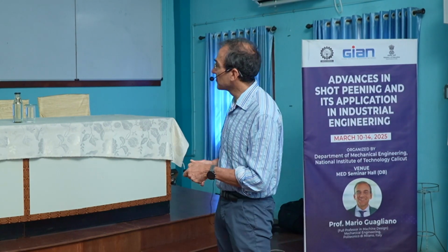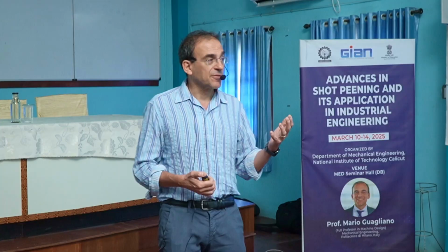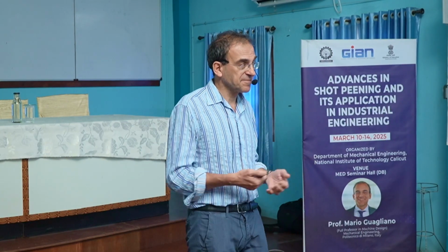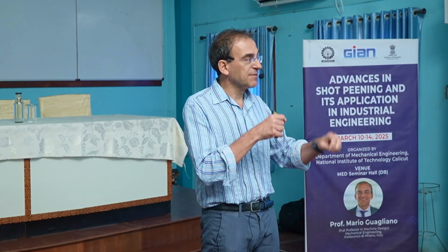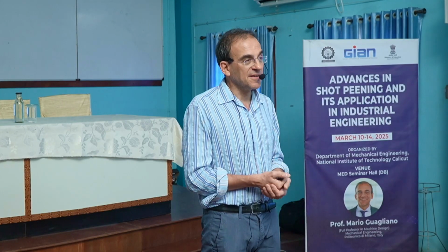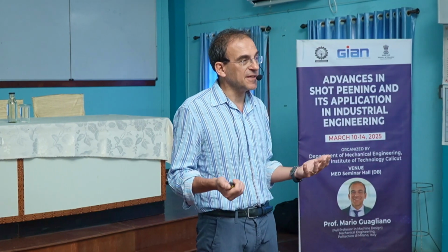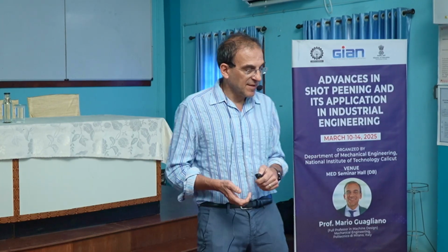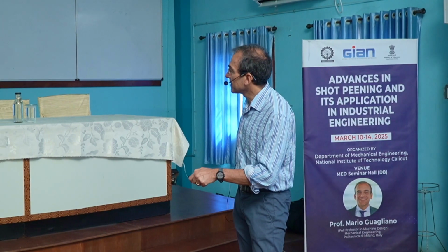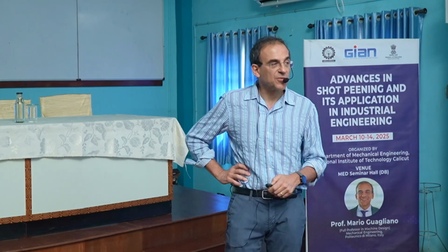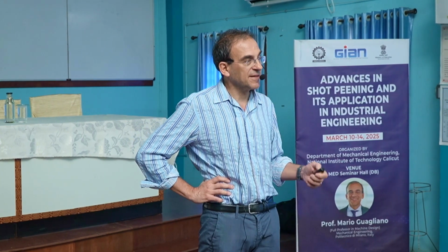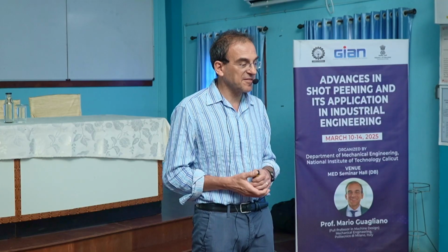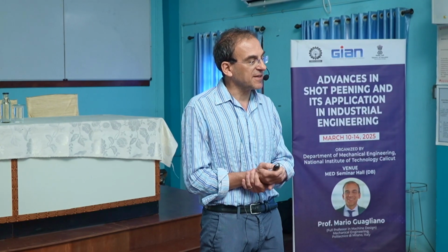in such a way that the result can be extended not just to the representative unit, but to the large part. We must also consider that the nature of shot peening is random. We do not have any preferential combination of the impacts. They are quite random. And then finally, we need a relation that makes it possible to relate the simulation result, the finite element result, to the real coverage value.